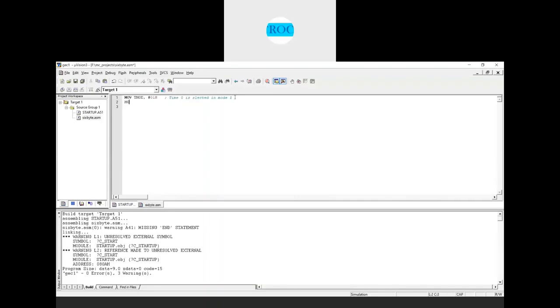Next we need to initialize the registers. Which registers? Since it is timer 0, TL0 and TH0. MOV TL0, #0FAH, right? Since it starts with an alphabet, we start with 0. So that what we have done, so that the TL0 is equal to what now?